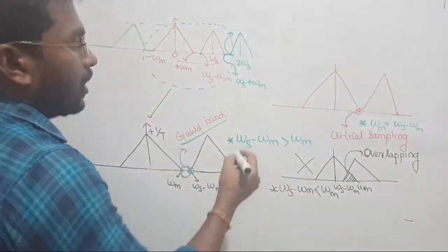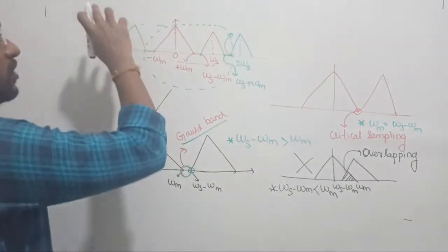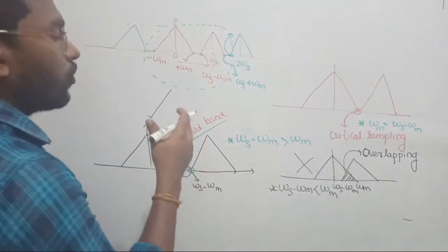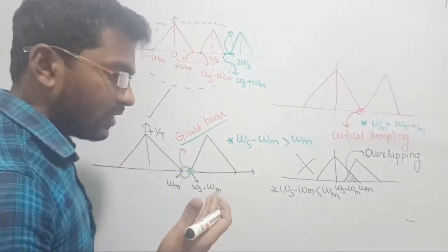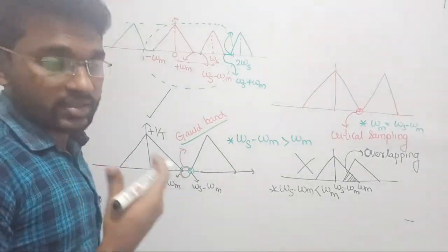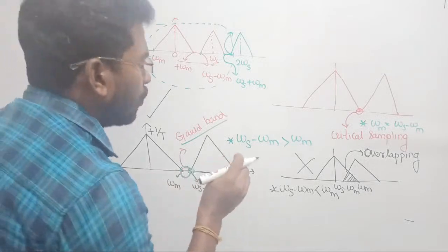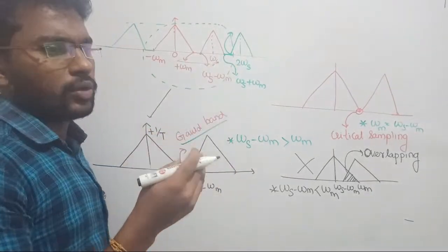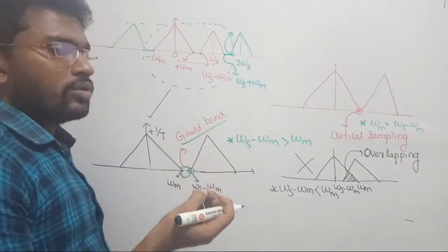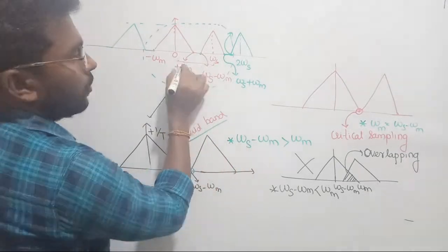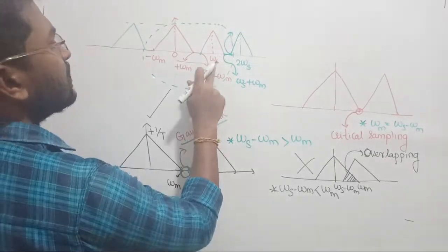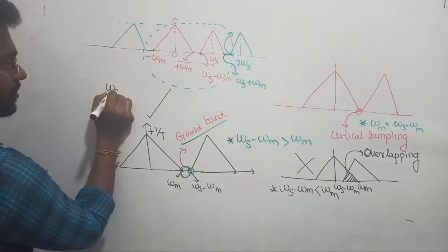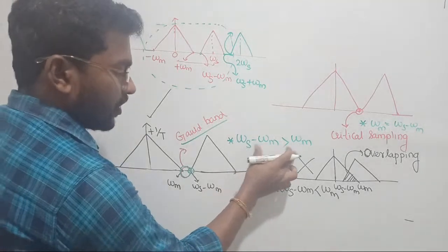So in order to do the sampling process, to construct the signal properly, if you want to transform the signal from the continuous domain to the discrete domain with this sampler, you will have to maintain something, right? The sampler keeps a gap, which is the sampling frequency you define. How much gap should be given between the first information and the second information is the frequency of the sampler, that is called the sampling frequency. Now, what can the condition of that sampling frequency be? See, let us take this function and reduce it.